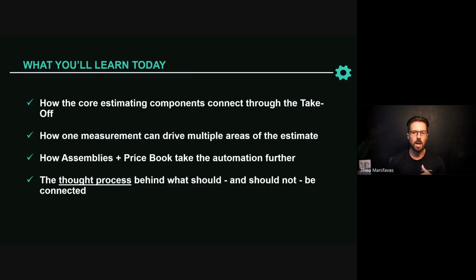So that last point, that's a big one for me, because it's easy enough per se to go build an estimating template and throw all these things into it, but it's really the thought process and the logic that goes into not only how everything's connected, but what should be connected to your takeoffs and back from your cost items in the estimate template. So I'll discuss that a little bit as we get to it, and then that'll sort of get the juices flowing from your end in terms of how you should be thinking about it when you're building out your main template.